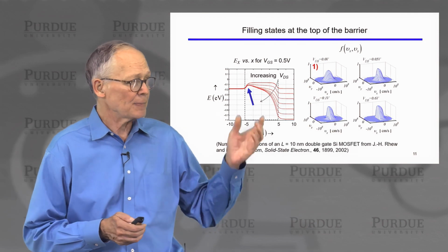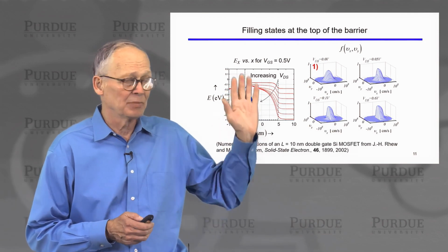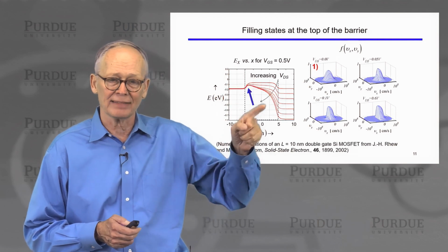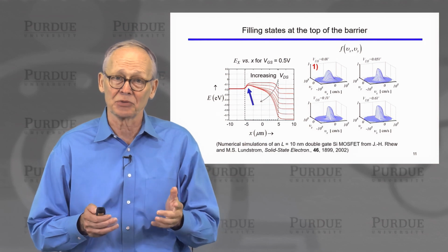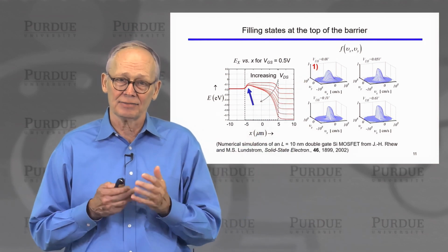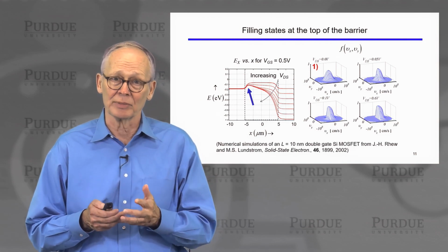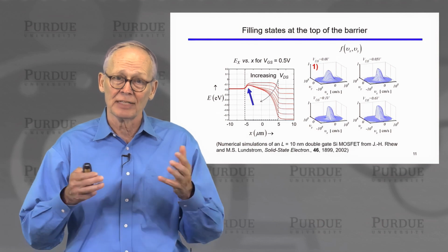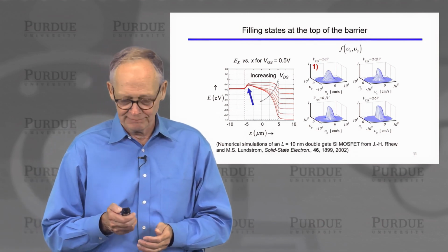That's right. All of the scattering occurs in the source and the drain contacts, but we have injected the positive half of this thermal equilibrium distribution from the thermal equilibrium source, and we have injected the negative half of that distribution at the top of the virtual source from the thermal equilibrium drain. Put those two together, we get an overall thermal equilibrium symmetrical distribution.